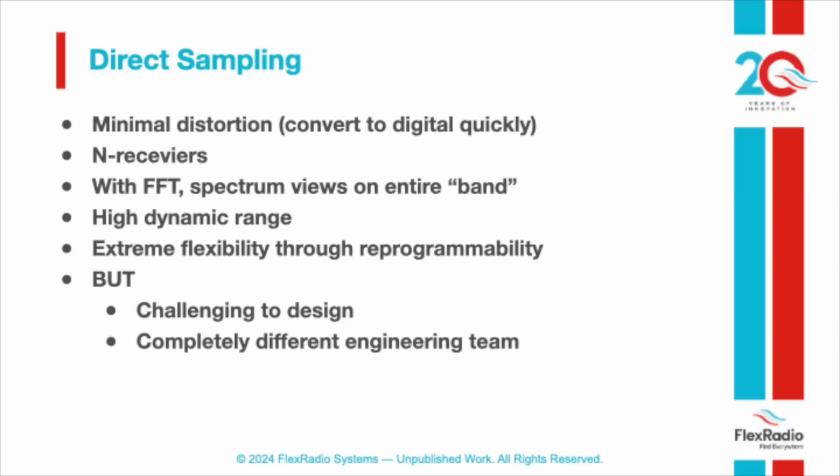The other really cool thing about this is that once you have the data from that antenna, you can take that and copy it and use it multiple times and make as many receivers as you want in that radio, which is a really cool thing. If you look at what happened in the analog world, even 10 years ago, you go buy a radio, and if you bought one that had one receiver, it was N dollars, and if you bought one with two, it was N times 2 or something, because you had to have all that second set of analog electronics to do that. In a radio like this, you can add an additional receiver with just more compute power, so it becomes a lot less expensive.